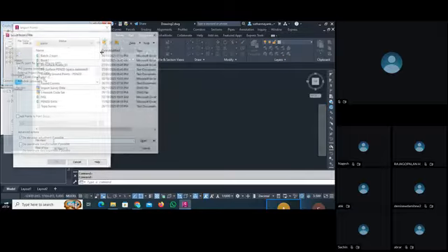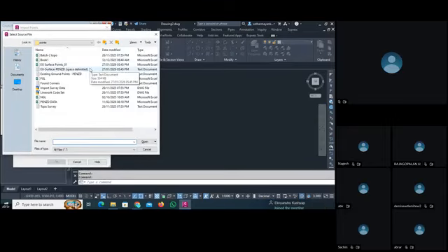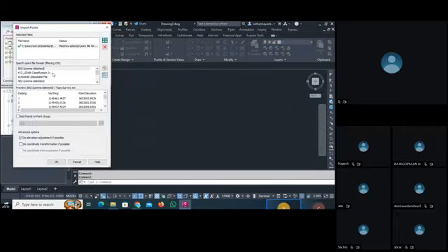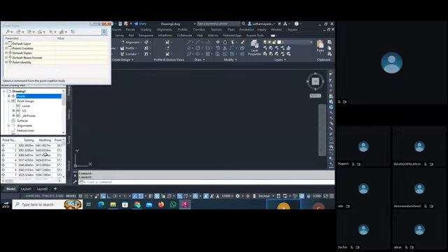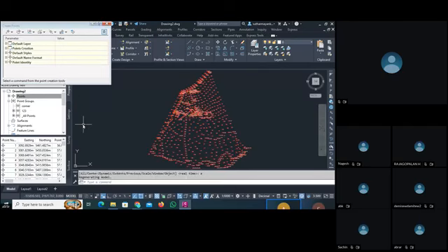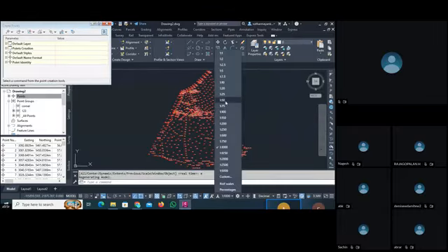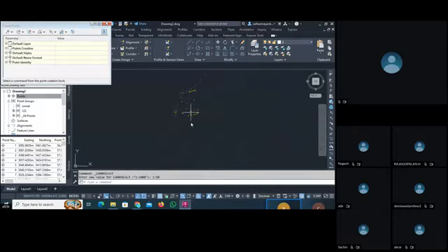As you repeatedly use these things, you will never face difficulty while importing. We select our point style, all okay. Now we have a group. I create the 1, 2, 3 group for all points. I select 1, 2, 3 and then give okay. Now all my points are inserted. Then to show the points, I type Z enter, E enter, and I scale it as low as I can, 150. Okay, now it's all right.